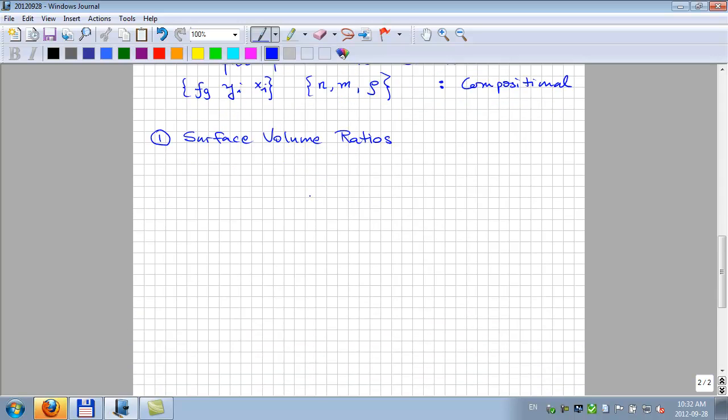Okay? And there are two of them. There's capital Rs, and it's defined as the surface gas volume divided by the surface oil volume, where the mixture zi, the mixture we're talking about, is an oil phase. In other words, this zi is representing an oil. So if you see Rs, it is telling you something about the oil phase, not about the gas phase.